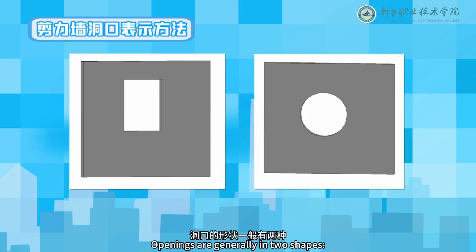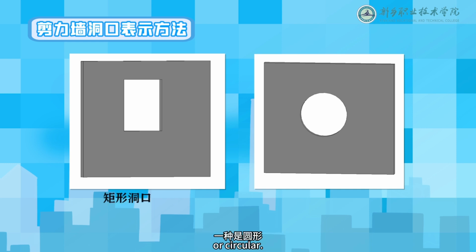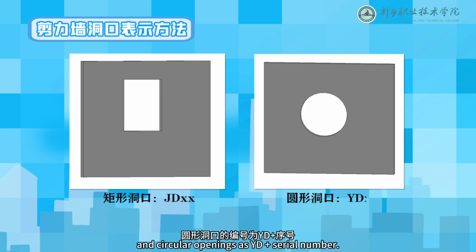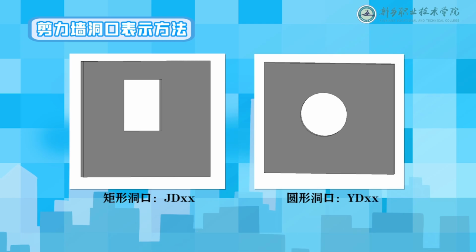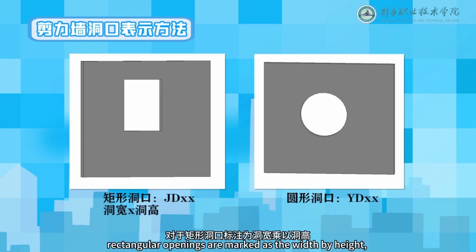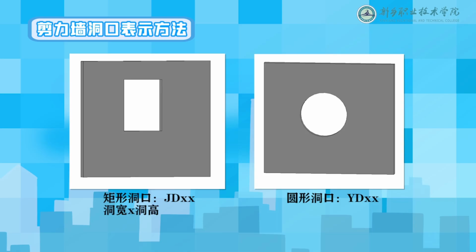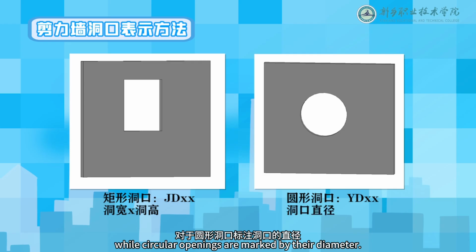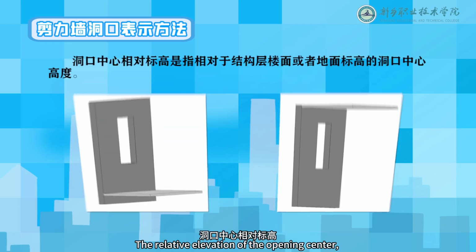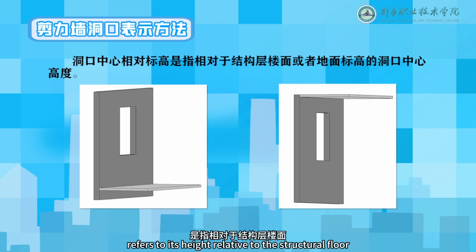Openings are generally in two shapes: rectangular or circular. Rectangular openings are numbered as JD plus serial number, and circular openings as YD plus serial number. For the marking of opening geometric dimensions, rectangular openings are marked as the width by height, while circular openings are marked by their diameter.